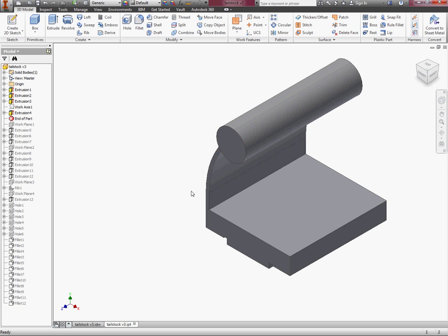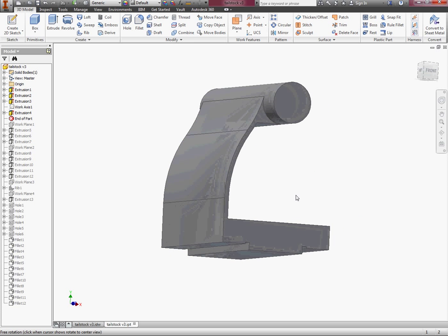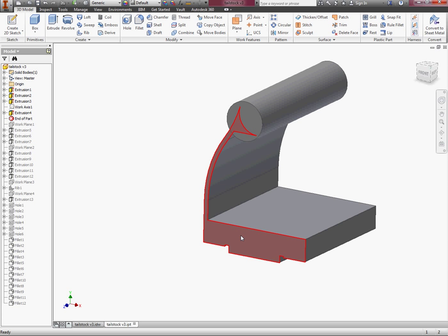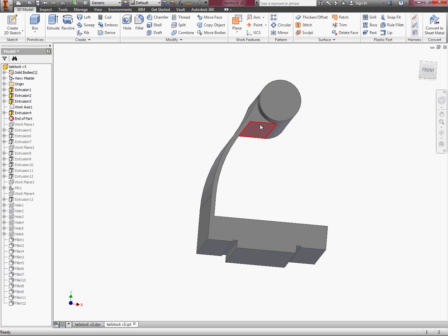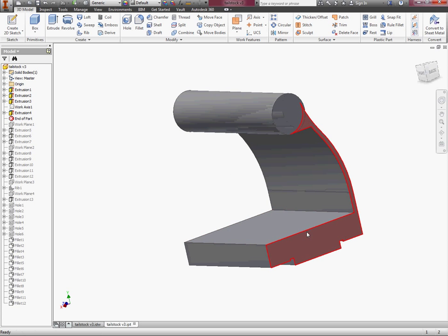Next, we make the pedestal, or the gooseneck that supports the cylinder. As you can see here, again, we sketched on the end of the base, figured out the shape we needed. Don't forget the little flat part here before you extrude that back. And then just extrude it to the other end of the base.